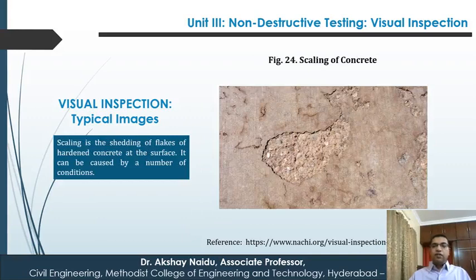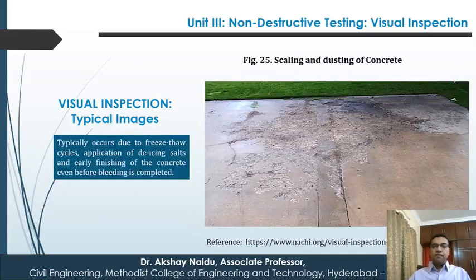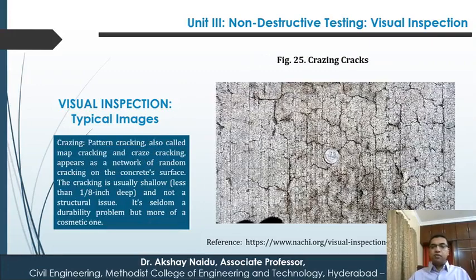This is scaling of concrete, which can occur due to various conditions, weather conditions or improper surface finishing. Then scaling and dusting of concrete. Okay, in typically cold countries, this may be the reason. The reason can be freeze thaw cycles and application of de-icing salts, which cause problems.